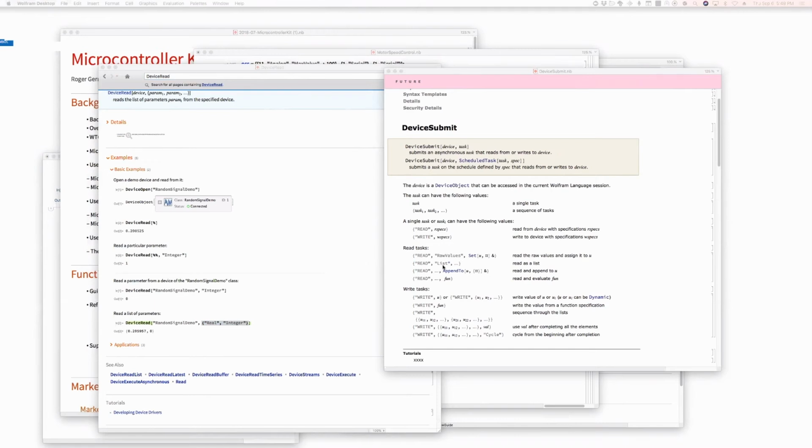Okay, listen this time. I'm saying if you've got, let's say, just two things, temperature and humidity, coming across the wire from the microcontroller. What I understand is that first it sets U to temperature, then it sets U to humidity. Is that correct? No, with raw values, it will just set till the delimiter byte, whatever is coming, will be set to U.